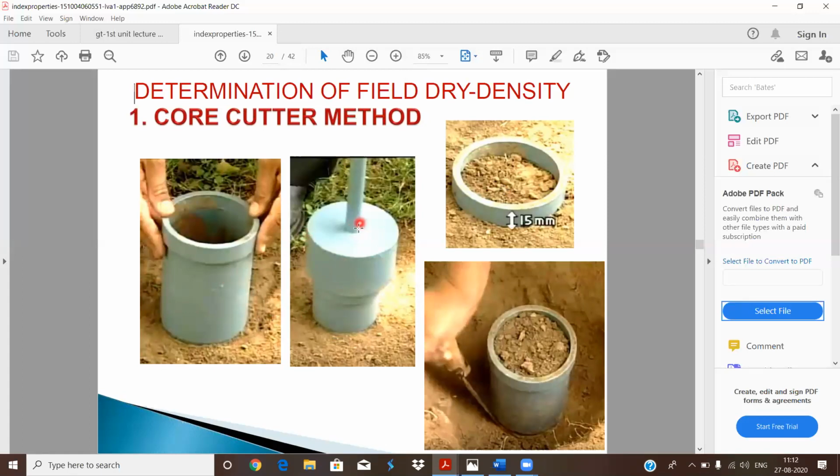On this top we apply the rammer to give compactive energy. By giving compactive energy, the cutter is slowly driven into the soil. Finally, we reach the point where only the dolly is penetrating. The total height of the dolly is 25 mm.